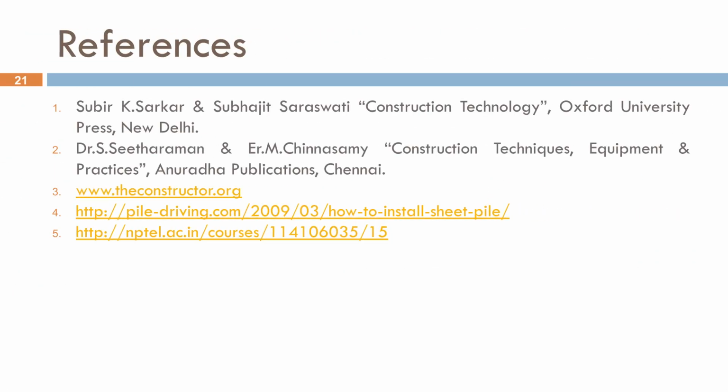Let us recap. Pile foundations are deep foundations used when upper soil layers cannot safely support structural loads. We discussed the functions of piles and learned that loads can be transferred either through end bearing, skin friction, or a combination of both. We studied pile installation methods, including rotary bored piling, continuous flight auger piling, tripod bored piling, dropping weight hammer, vibratory piling, and the jacking method.